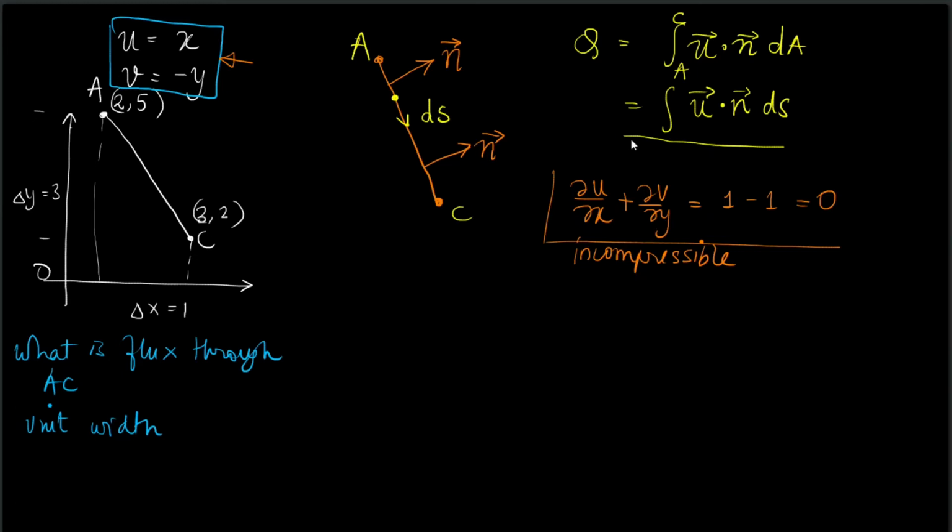And we know from the elementary considerations of a stream function, an incompressible flow field can be written in terms of a single scalar which defines the stream function. So we can write u as del psi del y and v as minus del psi del x. And you can of course swap the sign of this. It makes no difference as long as you keep the signs consistent.